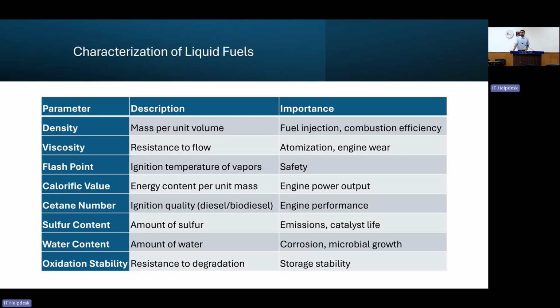Flash point is also important for the ignition temperature of the liquid vapors in the engine, and this is very important for safety. Calorific value, similarly cetane number, sulfur content, water content, and oxidation stability are mostly considered for the suitability of liquid fuels as drop-in fuel.